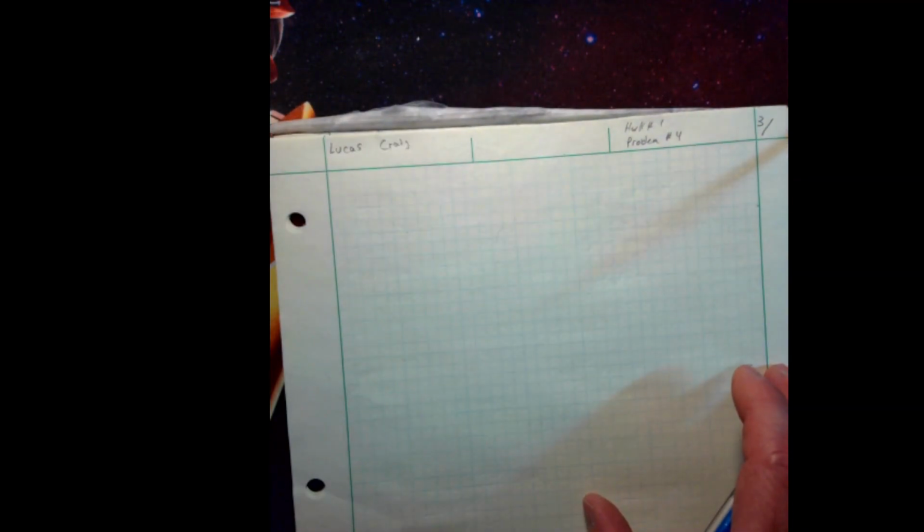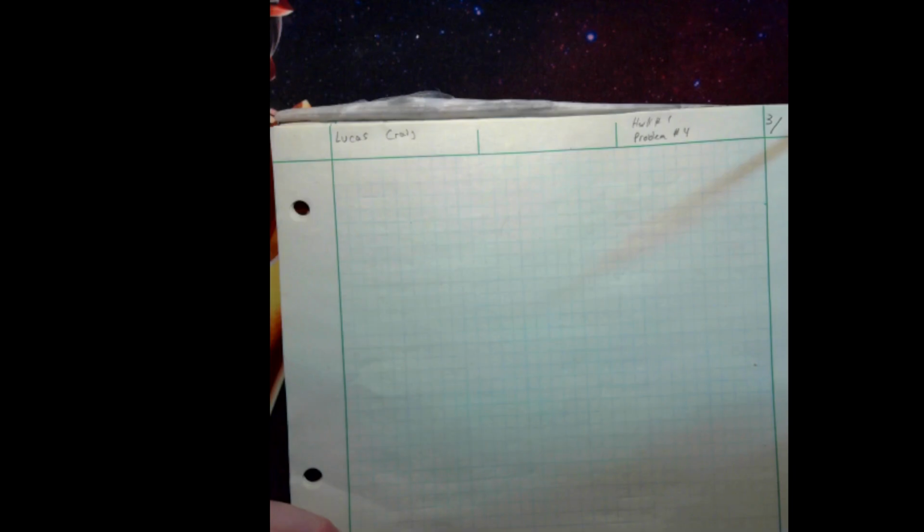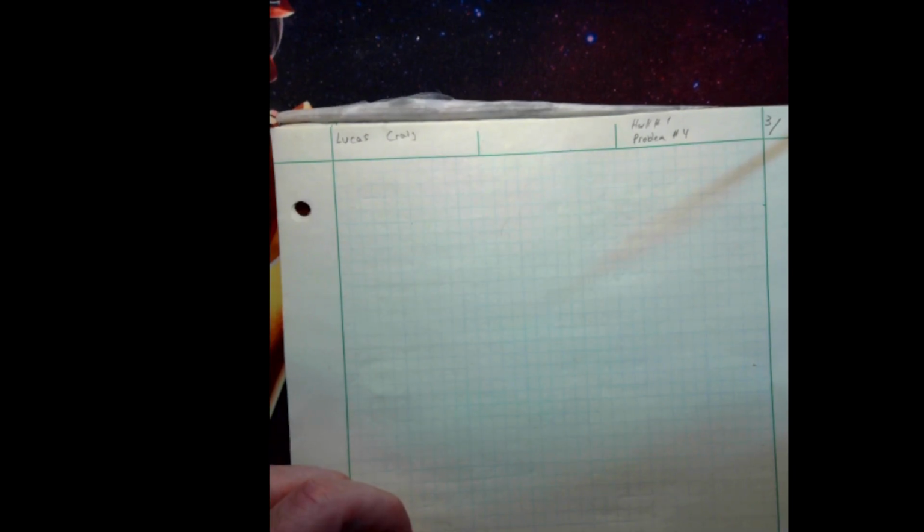We're on this last one, which is the falling ball viscometer. A steel ball is 1.6 millimeters in diameter. It's allowed to fall, having a specific gravity of 0.94. Steel weighs 77 kilonewtons per meter cubed. The ball is observed to fall 250 millimeters in 10.4 seconds. Calculate the viscosity of the oil.